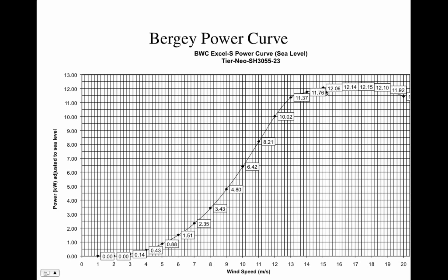wind. We'll go outside and look at that. We've looked at that, I think, on our original tour, but we'll go out again and look at that, and you can see the mechanism that this machine uses to actually spill the wind once it gets above a certain point, so that it can have a reasonably sized generator that doesn't get overloaded, and it just kind of throws the rest of the energy away by tipping away from the wind.